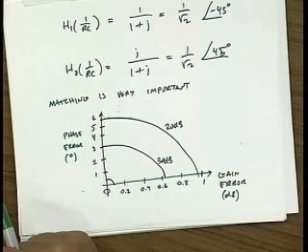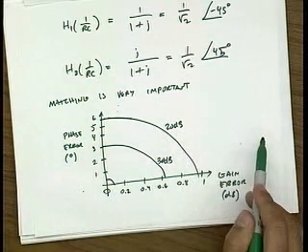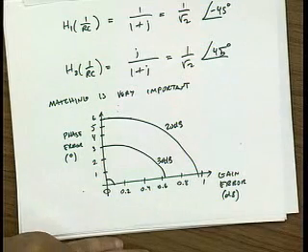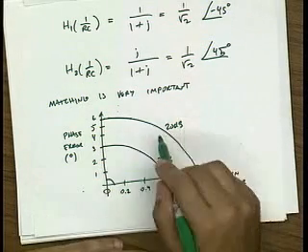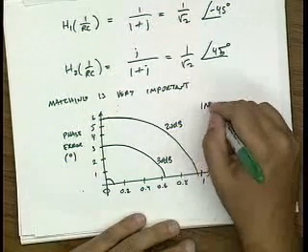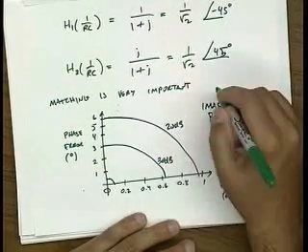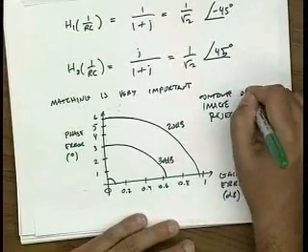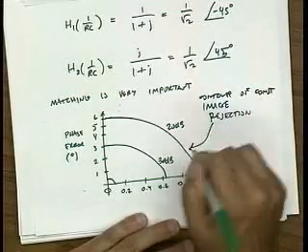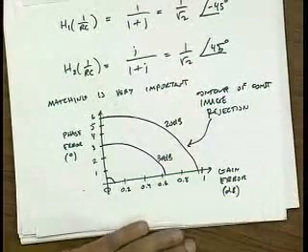Okay, questions? Don't you have it backwards? I mean, as more error, getting more rejection? No, no. If you have more and more gain error, right, you get less rejection. So 20 dB means I'm rejecting my image by only 20 dB. So this is the image rejection. So this is a contour of constant image rejection. Okay, that's 30 dB. I thought it was 3. Sorry, yeah, these pens are hard to write with.